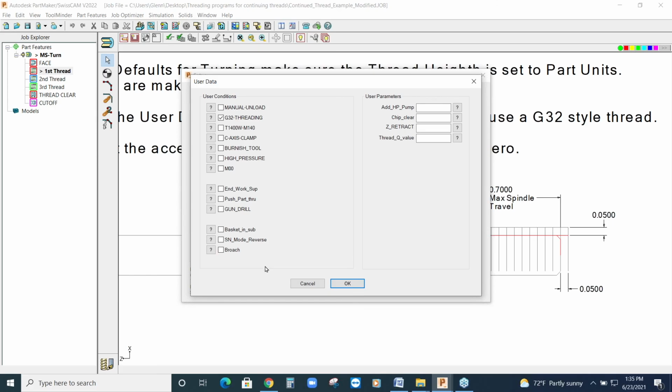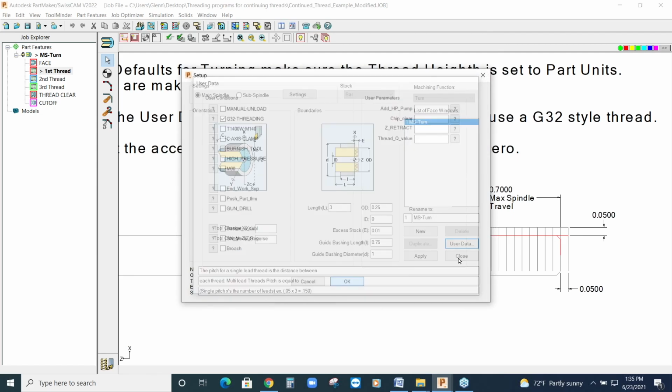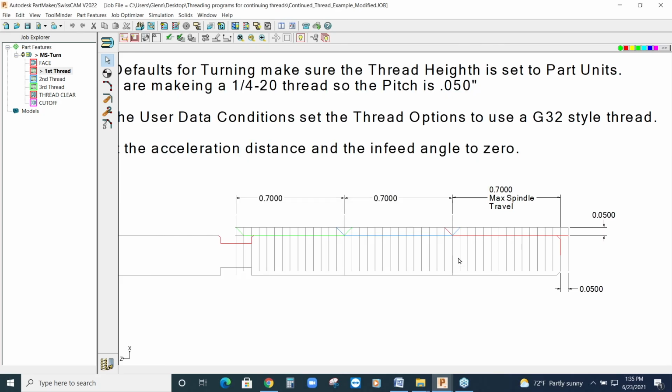Hopefully that answers your question. So just like we turned on a G34, you would somewhere have a G30 or a G32, you'd have an option to do the G34. Assuming the option exists, yes. You'd have to talk to the post developers to make sure it's in or could be put into your post.